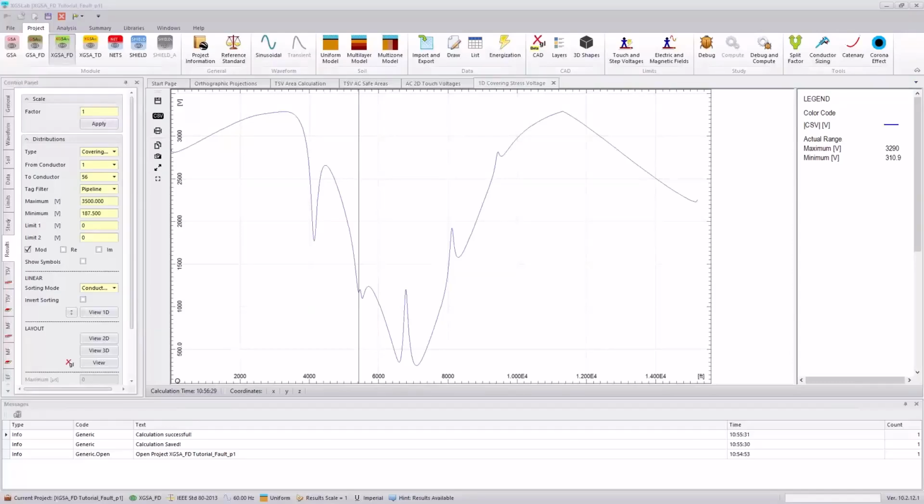Another question is, can we use XGS to calculate induced voltages on ungrounded shield cables? Yeah, so if the cable's ungrounded, then you won't have that induction as much, but once it has a connection point, then you can have some current going through it. If you do have ground on both points of that shield, then you can have the induced voltage and current on that cable, and that's something that you can analyze with XGS Lab.